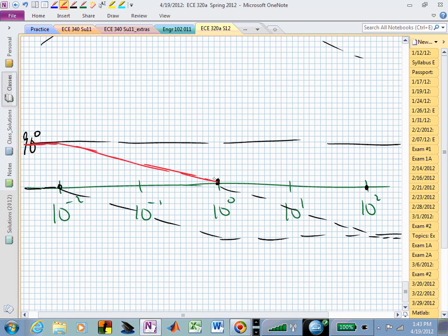And now what happens? We continue with exactly the same slope, don't we? We kicked off the slope due to the first pole, but now we have a second pole that just catches back up. And so this one is going to lay right on top of that, and that's what our phase looks like of H of j omega.